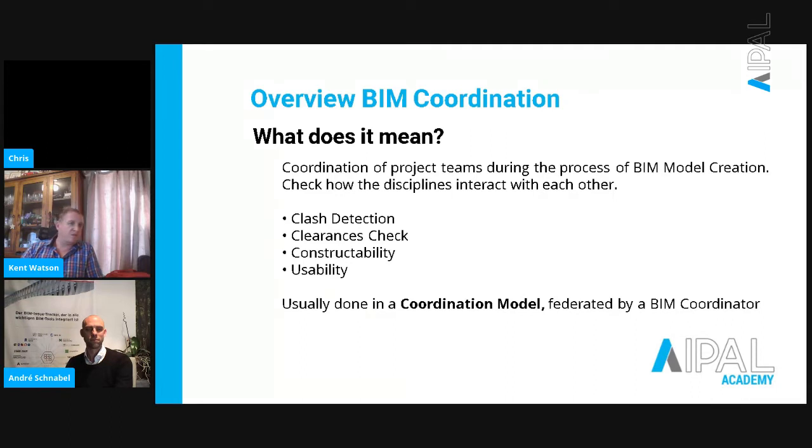Also, whether it's constructability or usability, but obviously buildings need to be maintained, and from your equipment rooms, you've got pumps that need to be pulled apart and put back together. So you need to make sure that there's the space for the pumps to be able to slide off the motors, or the motors to slide off the pumps, perhaps more accurately. So things like that. I'm not sure if they're things that often get checked, but they're certainly important to the functionality of the building.